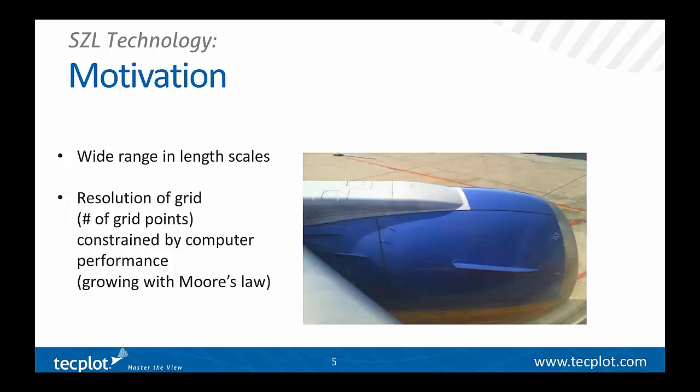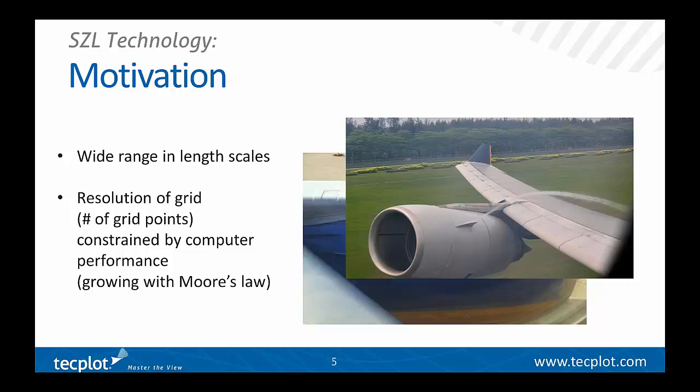It's called a fence, and it may look like it's just plastered on there as an afterthought, but it's actually placed and sized very carefully for one reason, and that is to create a vortex. It actually alters the aerodynamic behavior of the aircraft at high angle of attack. The reason you need that vortex is that the engine nacelle is very close to the wing.